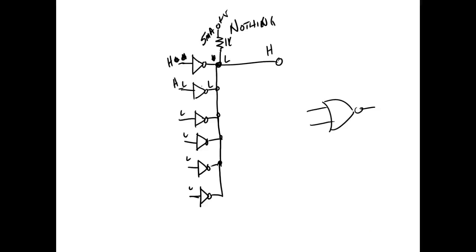So we refer to this, and this is kind of misnomered, by the way, because normally what we do is we put an inverter right here, and then what we end up with is an OR gate where I control the number of inputs. So this method right here, by the way, is called wired OR. They call it a wired OR gate. And the only way we can do that is if all these gates have to have what type of output?